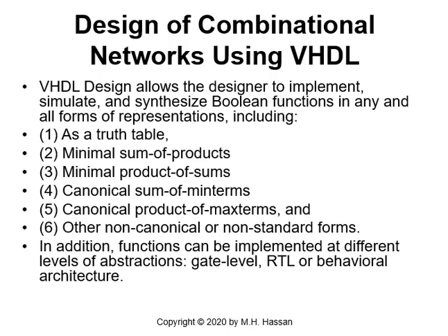The function could be a minimal sum of products, or minimal product of sums, or canonical sum of minterms, or canonical product of maxterms, and other non-canonical, non-standard forms. So in any form, we can use VHDL to implement the function, to simulate it, to synthesize it, and to download it into a complex logic device, FPGA, and so on and so forth.